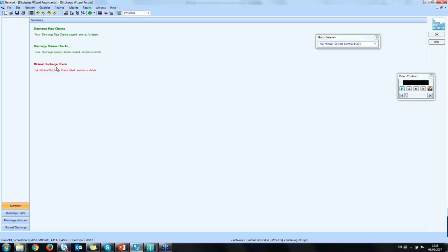So if you have zero discharge, so if everything went down to a soakaway or an infiltration basin, we would potentially have zero positive discharge. That's the only time this would occur. But in our case, we have a flow control and we are discharging something positively off-site through some form of flow control.